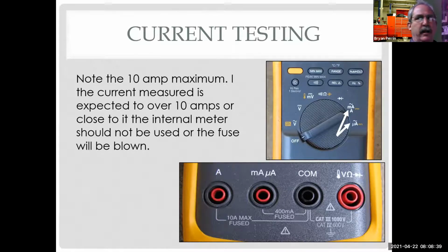I've done this a lot, and I was doing some electrical work. I had to put a new electrical line in my kitchen, and I was checking resistance on something. Actually, I wanted to check voltage, and I still had the meter hooked up to amps, and I popped the fuse. And let me tell you, at 120 volts, it made some sparks and all that stuff because it was a 20 amp circuit, 10 amp fuse. I blew the fuse in the meter, but everything popped quite a bit. And again, I just wasn't paying. It was early on a Saturday morning and I wasn't paying as close attention as I should have been. So things do happen, and you are going to blow fuses in the meter.